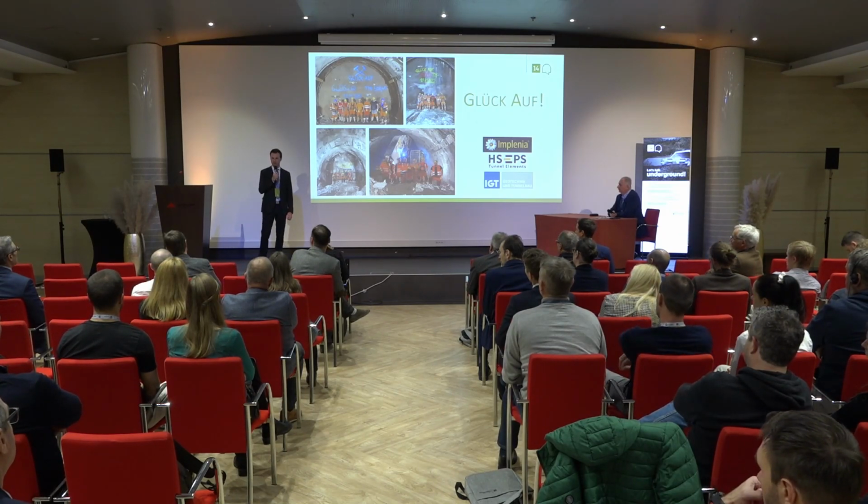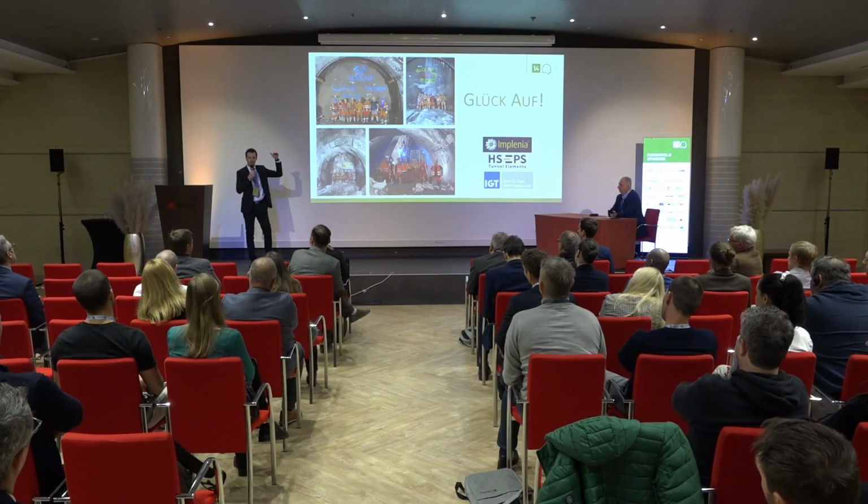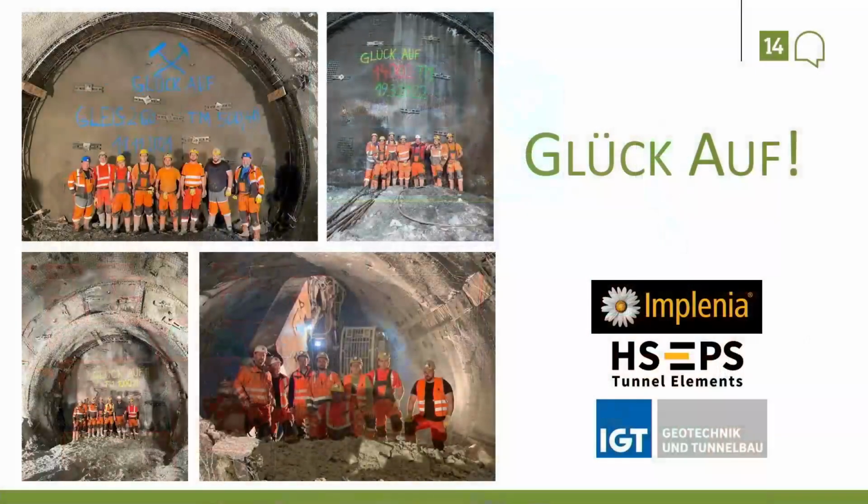Yes, of course. The combination would also be possible with a fiber reinforced shotcrete. In this case, the lattice girders are used, of course, to have a good shape of the tunnel, and in the next step, also for the installation process of the yielding elements. If you see here, for example, on these lattice girders, there is a steel bar fixed between the two lattice girders, and this is for the installation process of the yielding elements to be really fast.